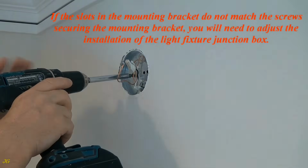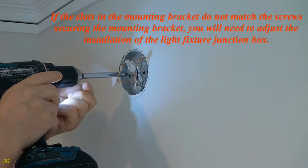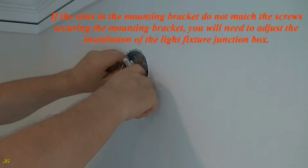If the slots in the mounting bracket do not match the screws securing the mounting bracket, you will need to adjust the installation of the light fixture junction box.